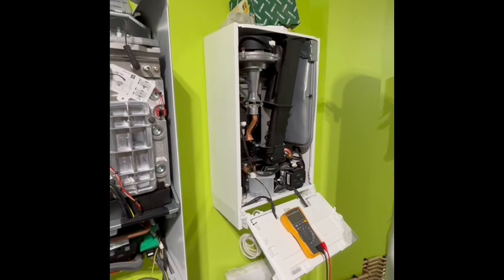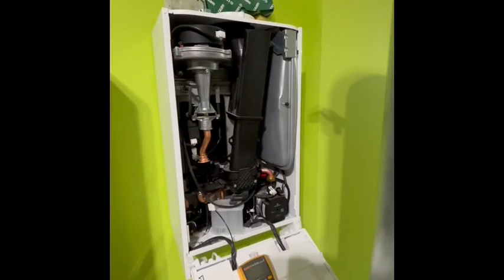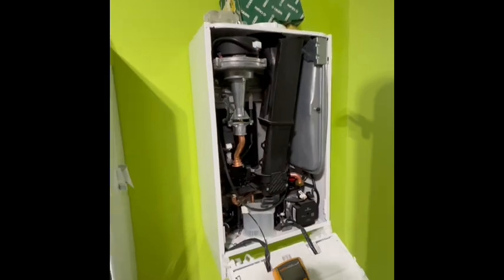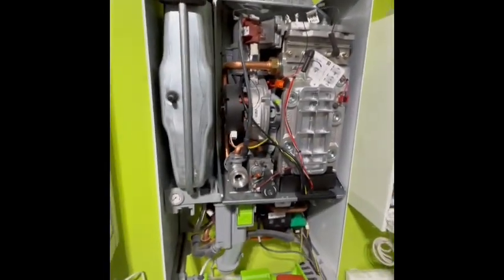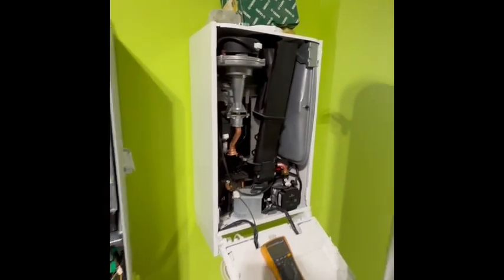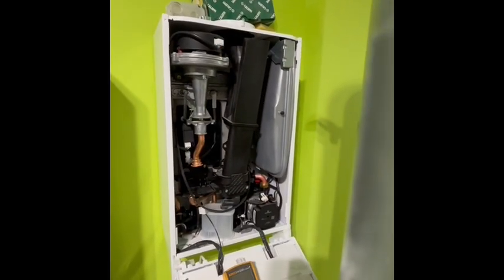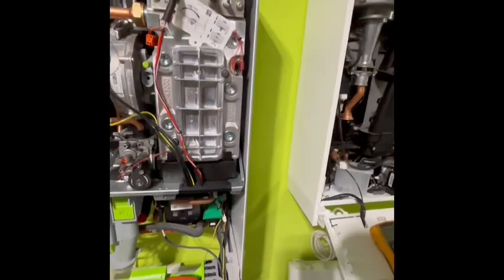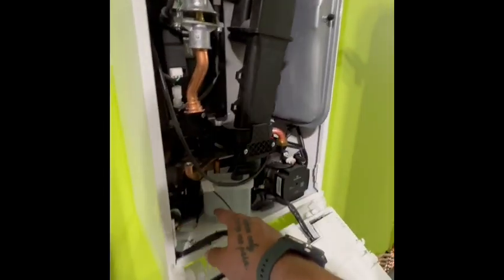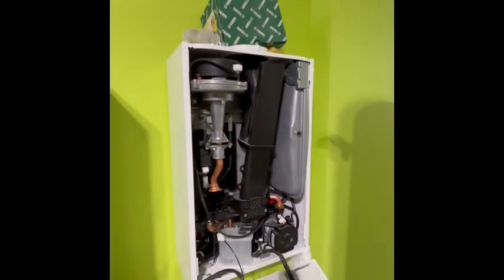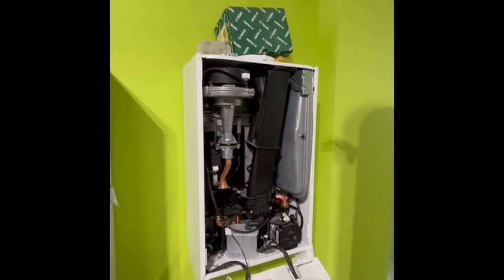Because what will happen is, as I said earlier, always ask the customer, is there any patterns of this boiler going off? Sometimes engineers will turn up, the boiler will run fine, and that's because there's a partial blockage in the condensed pipe somewhere and they just haven't run the boiler long enough. And all that happens is the water backs up down the condensed pipe, backs up through the trap, starts backing up into the heat exchanger, and then it starts restricting the air inside that heat exchanger.